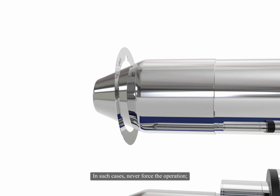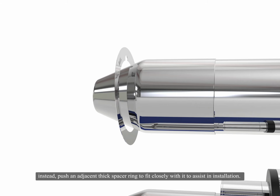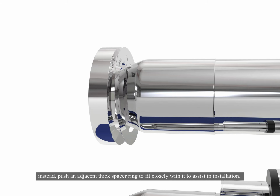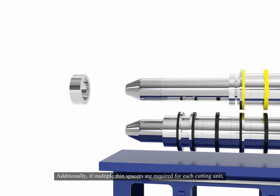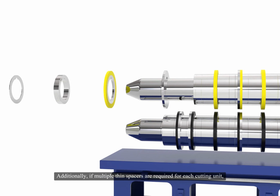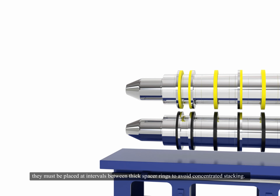In such cases, never force the operation. Instead, push an adjacent thick spacer ring to fit closely with it to assist in installation. Additionally, if multiple thin spacers are required for each cutting unit, they must be placed at intervals between thick spacer rings to avoid concentrated stacking.